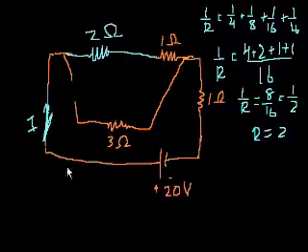And let me draw, I lost some wire here. I want to make sure the circuit can still flow. So that easily, I turned that big hairy mess into something that is a lot less hairy. Well, what is the equivalent resistance of this resistor and this resistor? They're in series, and series resistors just add up together, right? So the combined resistance of this 2 ohm resistor and this 1 ohm resistor is just a 3 ohm resistor.